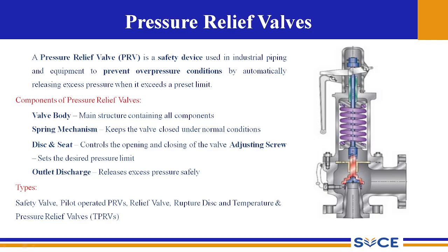So here you have the spring kind of an arrangement where the spring will be under tension and compression, and by excess pressure the valve seat or the disc seat will move up or down, so that the pressure excess buildup will be released by opening this valve and adjusting the position of this screw.